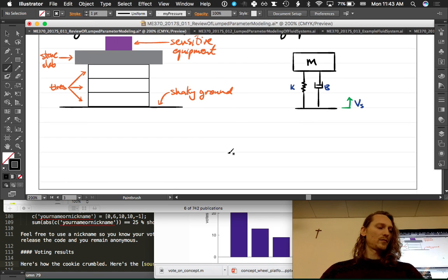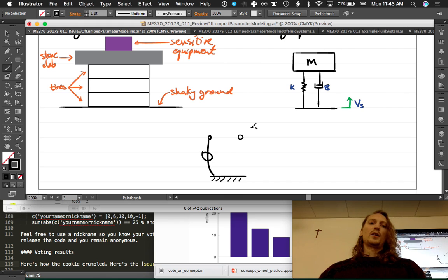We draw the ground. We always have to have ground, right? What other distinct velocities do we have in this system? The velocity source, so that's a node. And the mass velocity, that's another node, right? So we have the source here. Draw the arrow in a moment. Or sorry, not the force, the velocity source there. And then we have the mass always going to ground, right? Mass is always referenced to ground.